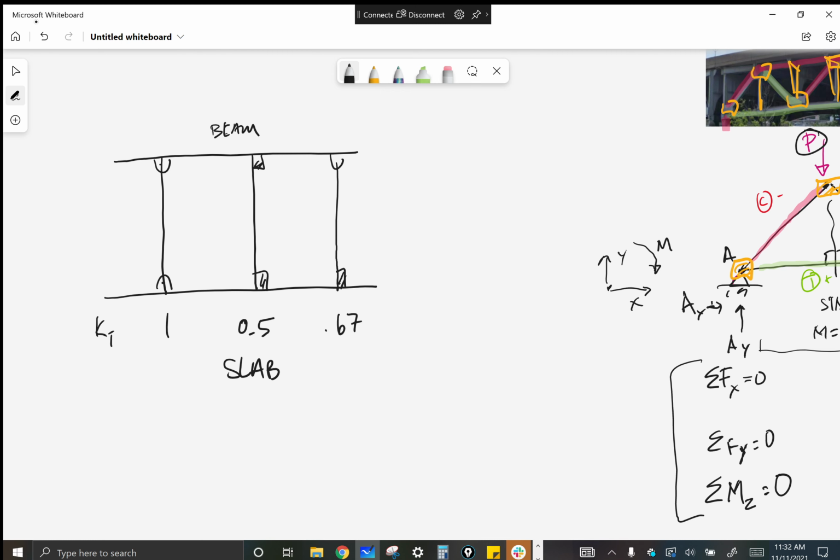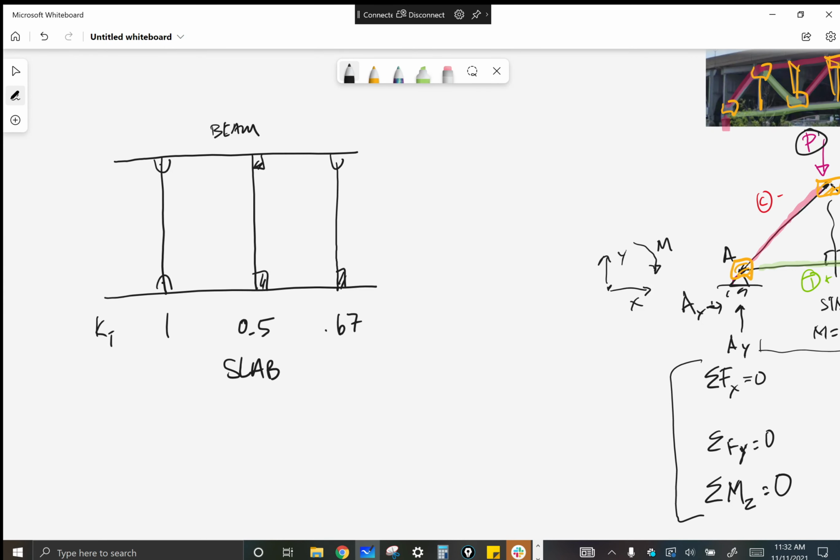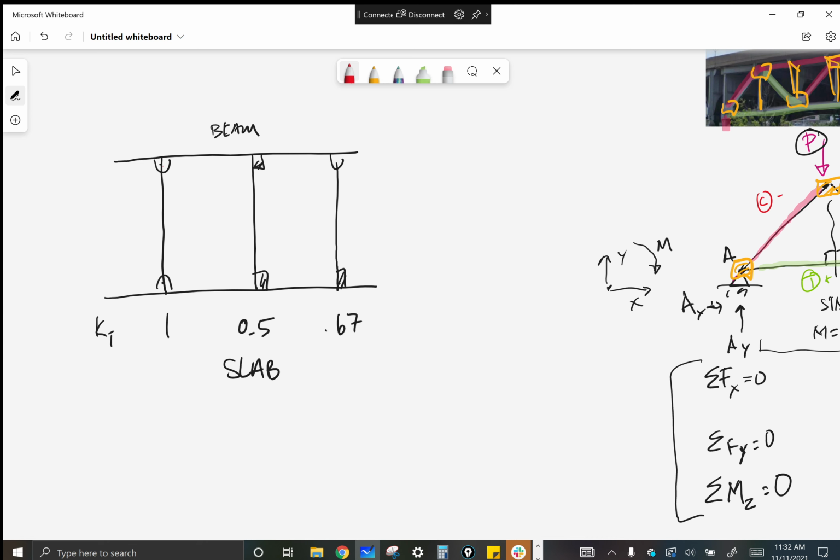Why is this? This is not calculus that was used to generate these numbers. It comes from this conceptually, at least in the way I understand it. In a hinged column, you have the entire length of the column, LU, available for buckling, right? So 1 makes sense, the entire length.